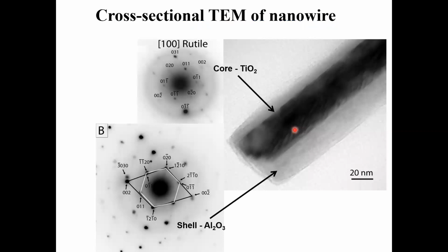So one question that we struggled with is, why is it forming one-dimensional oxide and not covering the entire surface with an oxide layer? Indeed, if you exceed the oxygen content in your gas environment to more than 100 ppm, we have seen you actually grow a thin film of oxide.